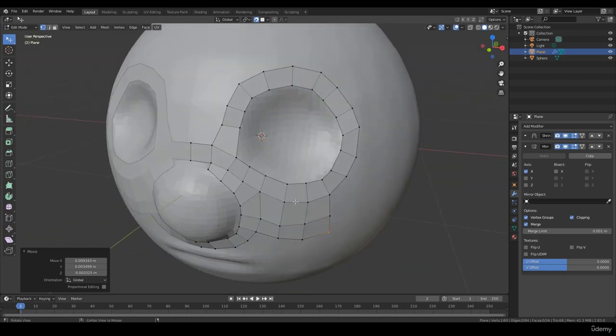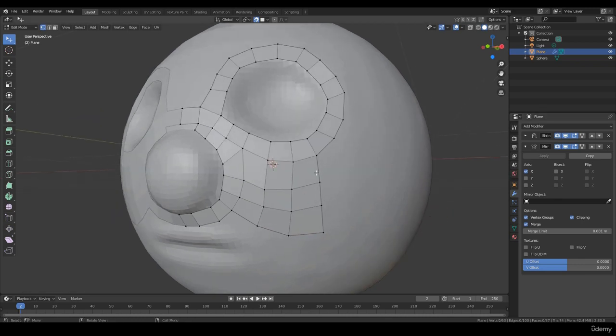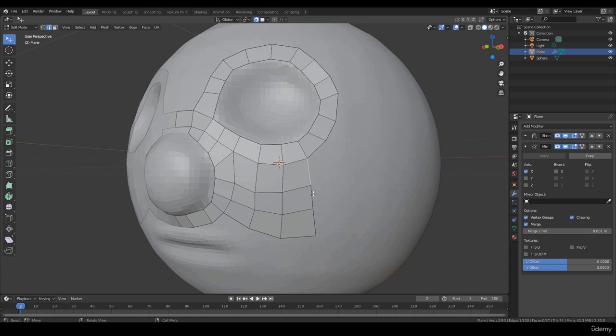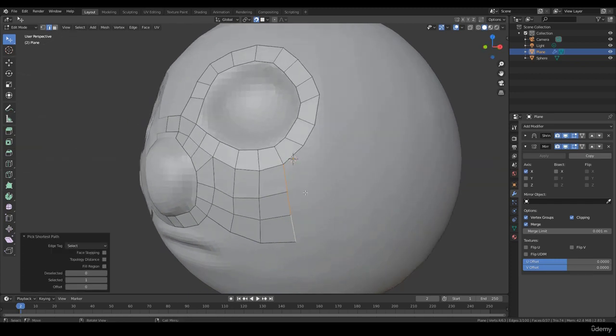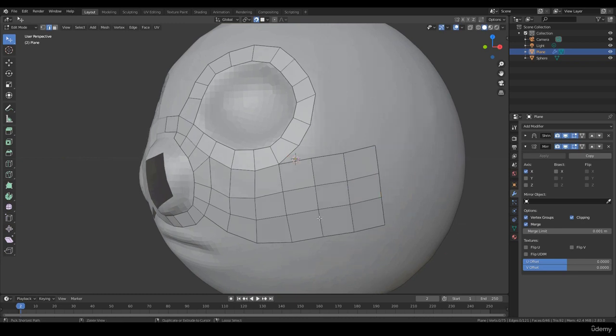And let's say I want to just create a lot more geometry here. Let's say I want to go to the edge mode, edge select, and select all these edges. I could extrude them all at the same time. I could press E, extrude, extrude, extrude. And I could go Control R and add some edge loops here.